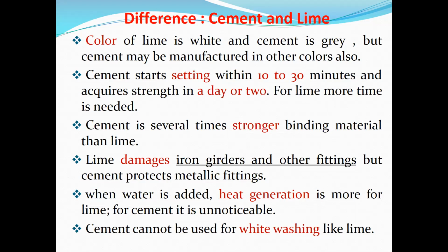But in case of cement, heat is also generated, but this heat generation is unnoticeable, negligible. Okay, but again, this is not that negligible, because if the construction work is very huge, or you are going for massive construction, for example concrete constructions, maybe you are making an earth dam with concrete, or you are using cement, at that time you see that a huge amount of heat will be produced. And that heat produced by cement is not negligible.